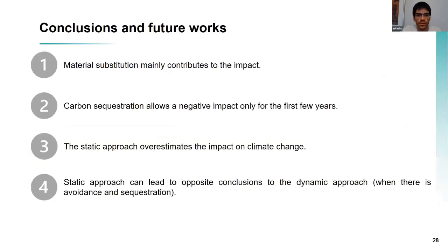So to conclude, the substitution of steel and concrete is the main driver of the benefit, and the carbon sequestration also allows for a benefit, but for the first years and depending on the end-of-life scenarios. And the static approach overestimates the impact on climate change. And finally, with a dynamic life cycle inventory that contains emissions, sequestration and avoidance that do not occur at the same time, the static approach can lead to a conclusion opposite to the dynamic approach.